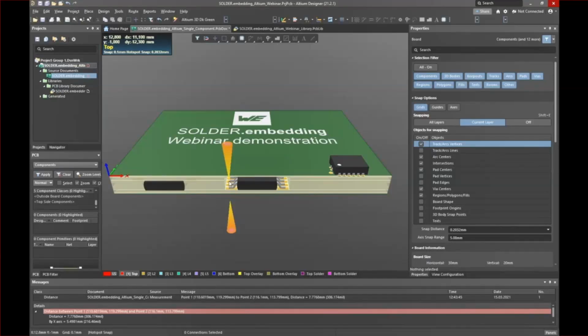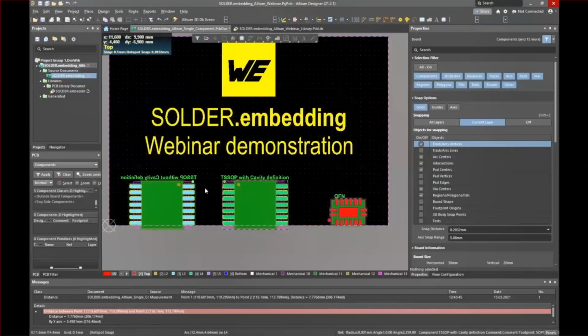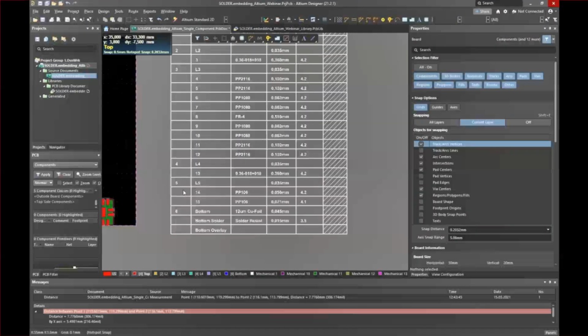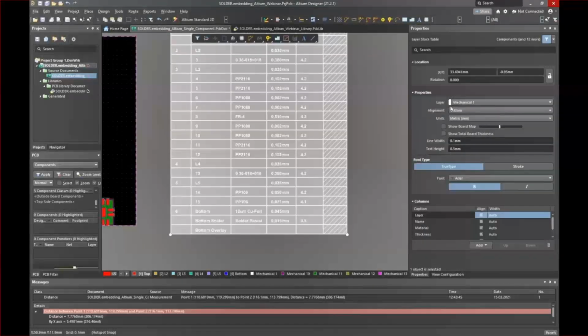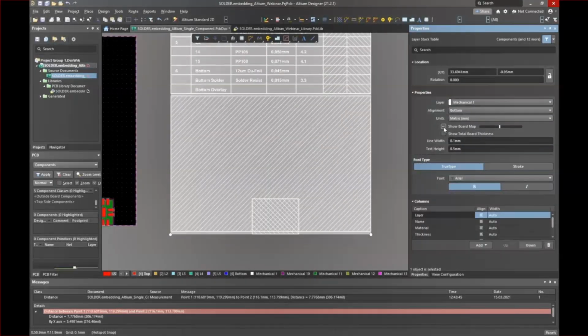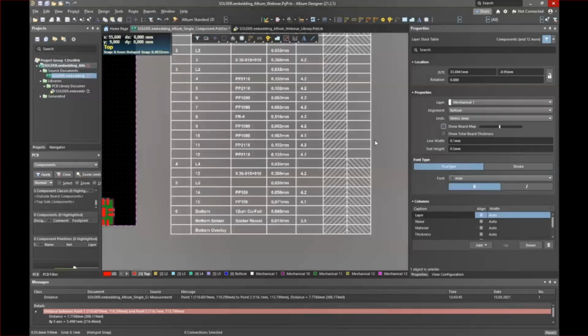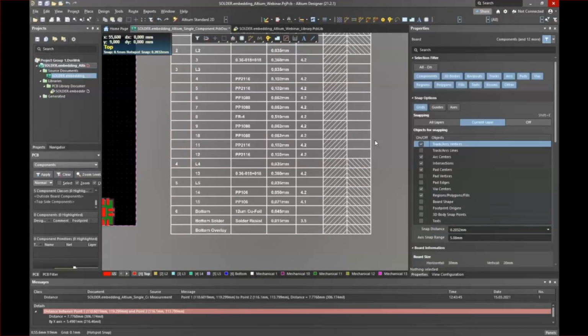So we switch to 2D. Since Altium Designer does not perform a Z-axis design rule set, unlike other tools, you can at least check here very well whether the part fits into your layer stack. Unfortunately, to do this, the layer stack table managed by Altium must be forced to update itself by making a small change. But after that, you will see the additional stack with the Z-axis clearance, as you can see here in this case for this second stack.